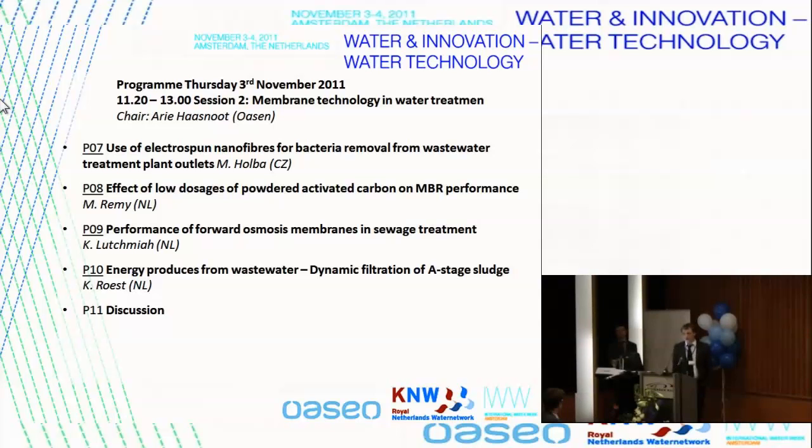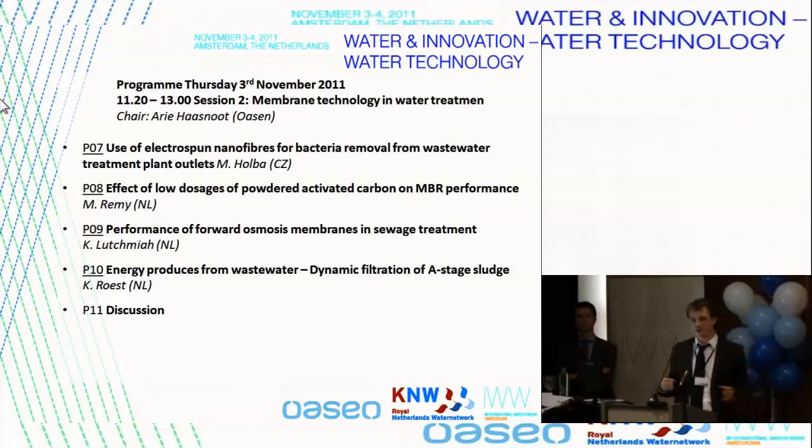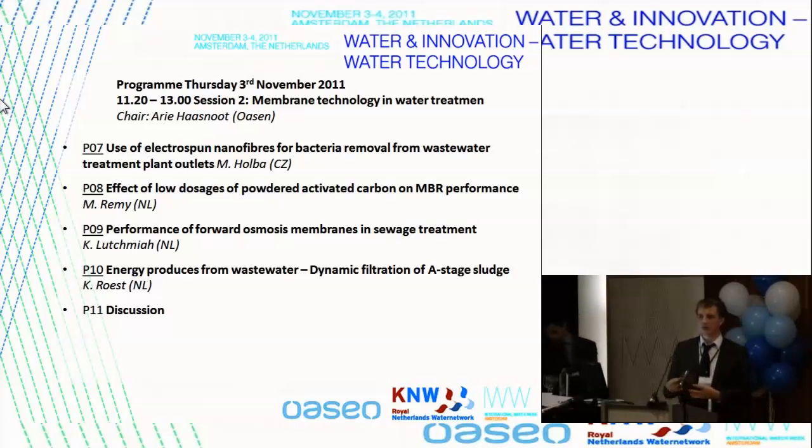I did try non-activated powdered carbon, which is just carbon powder. What I find interesting with the carbon is actually the density, which is quite close to the floc. So instead of a sand that would settle quite easily, with the carbon, it stays within a suspension, and then it makes flocculation more likely. I did those tests with powdered carbon when I was investigating the mechanisms, in order to see if we had a similar effect with non-activated compared to activated, in order to rule out the adsorption. And I did find also positive results in that case.